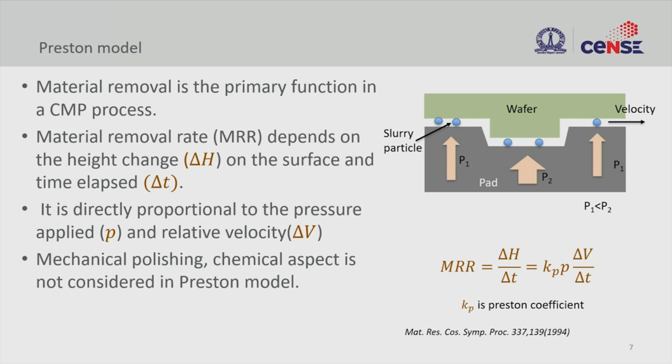So, the material removal rate, right. How much material we remove depends on the height difference that we have between the flat layer here and the topography here, and also how much time we spend in this polishing. Okay. So, that is something which is straightforward. You can also take that as a ratio and that could give you your material removal rate, right. But if you look at it more carefully, it also depends on the pressure you apply, right, which depends on the height difference.